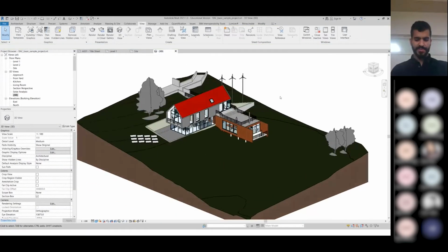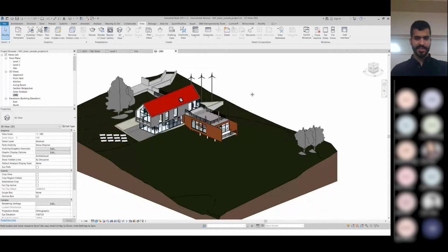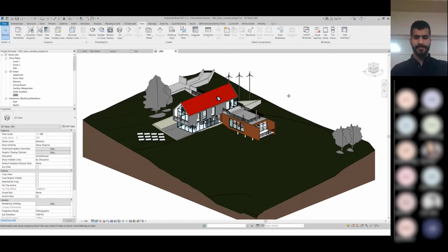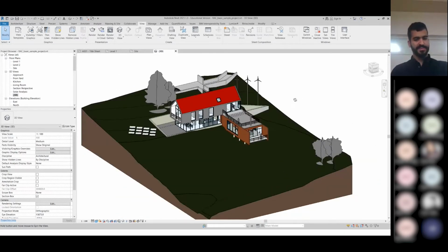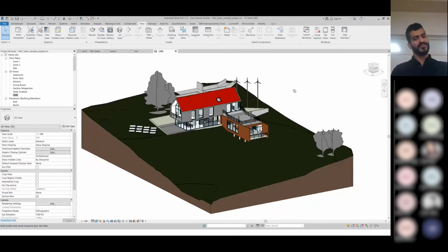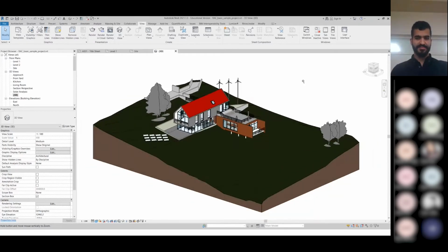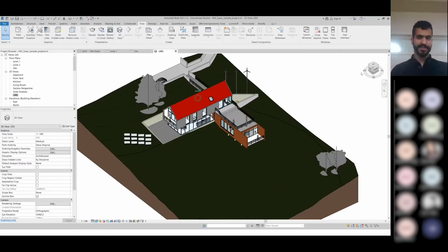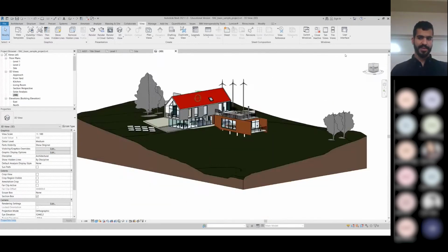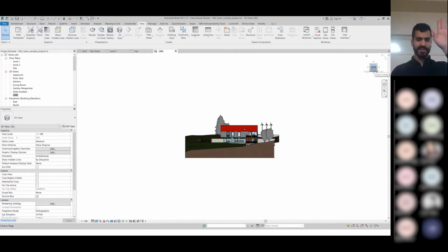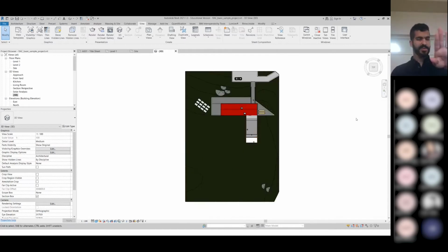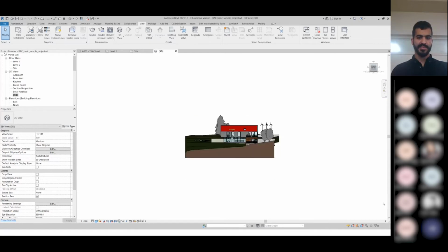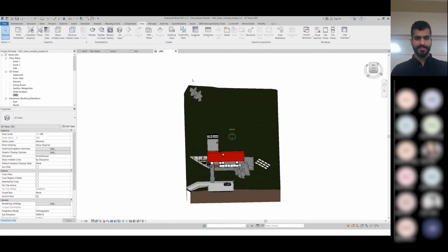If you press on your scroll wheel, can you pan? It's still just panning with Shift. With Control you zoom in and out. If you can't rotate with that, we'll fix it later, it might be something to do with shortcuts. But you can do it here at the top right. If you click on the front, it'll give you an elevation. The top will give you a plan, and if you hold the corners and rotate, you can rotate around. Okay. Thank you.